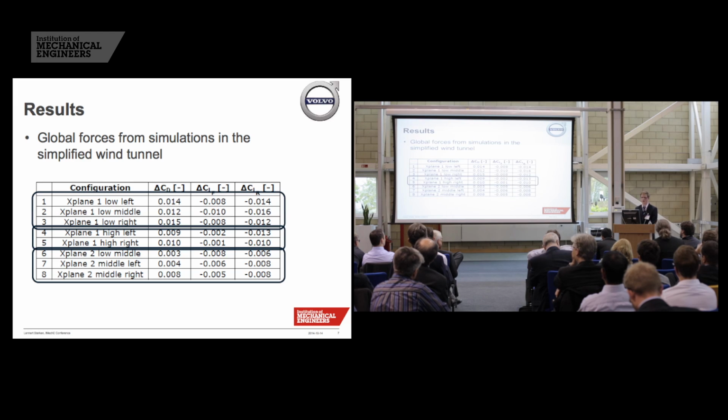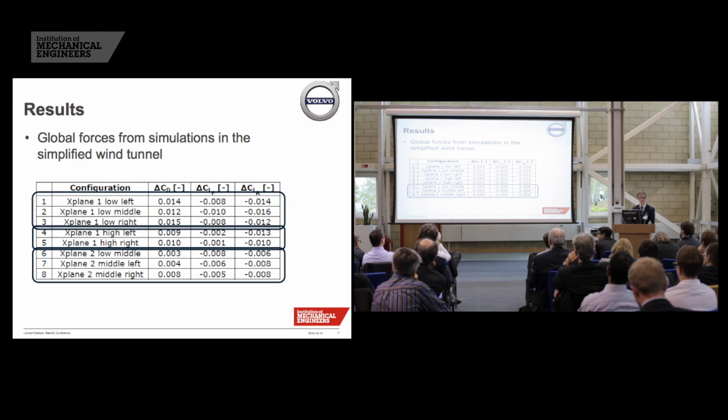A second division is the 100 millimeter plane, but measuring closer to the roof of the car. There you still had an increase of drag, but a little less significant than before, not so much front lift change, and still a rear lift change, with a decrease. Going further away from the car to 750 millimeters, we saw these effects start to reduce to much lower values.